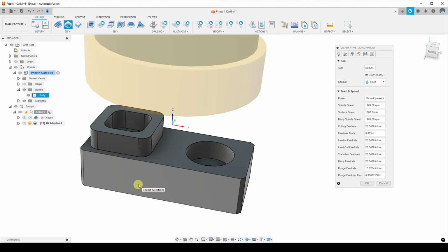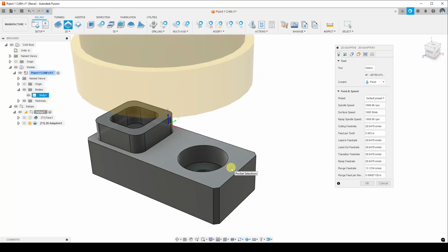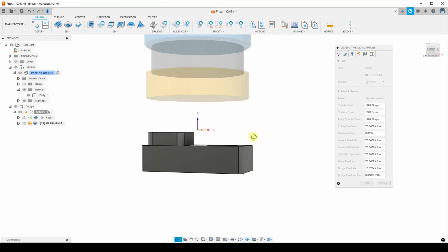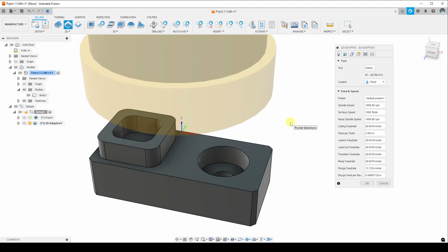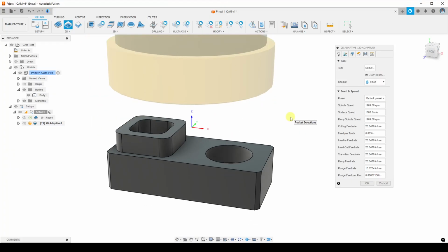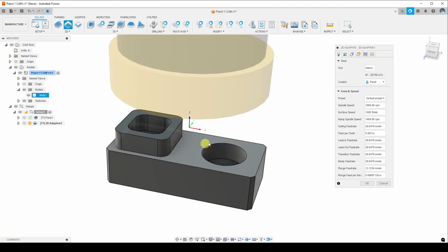That's going to reduce machining time, and it's a much more efficient way of machining. And you can only do it with CNC machines because you have really finite control over the motion of the machine. What it's effectively trying to do is limit the force on the tool, or the load on the spindle, to a constant amount. And it does that using geometry, which is actually quite clever.